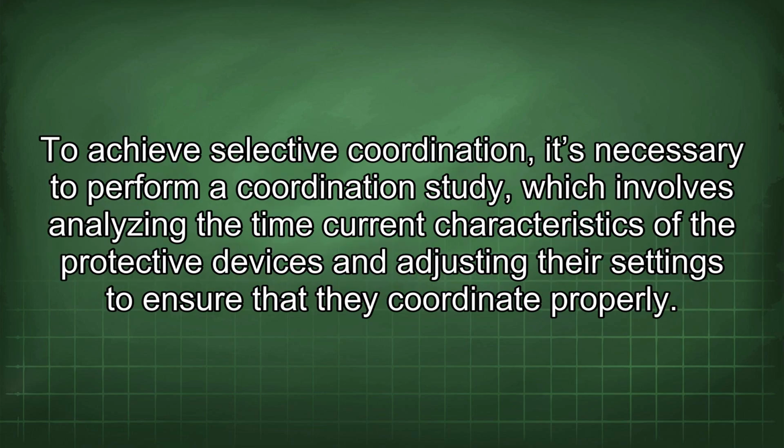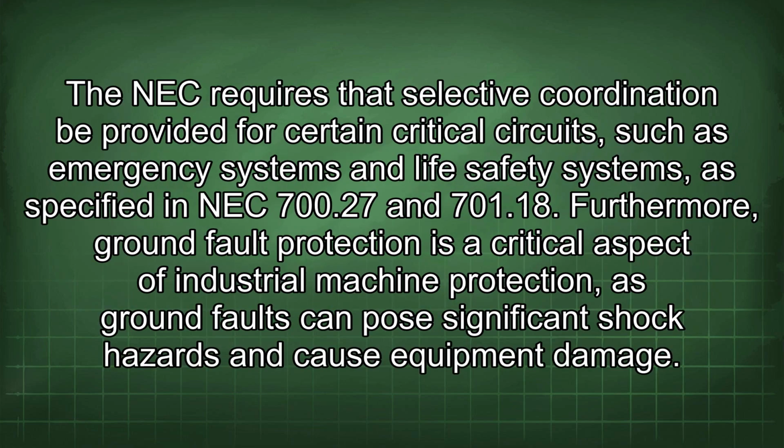To achieve selective coordination, it's necessary to perform a coordination study, which involves analyzing the time current characteristics of the protective devices and adjusting their settings to ensure that they coordinate properly. The NEC requires that selective coordination be provided for certain critical circuits, such as emergency systems and life safety systems, as specified in NEC 700.27 and 701.18.